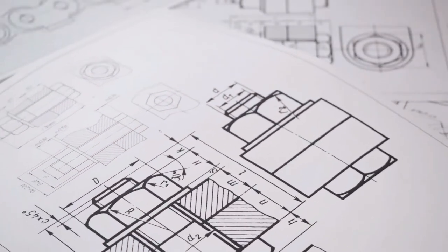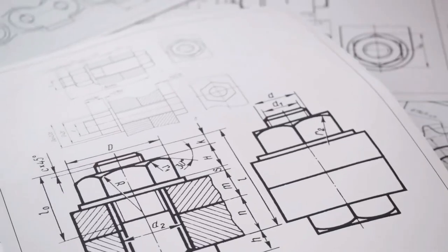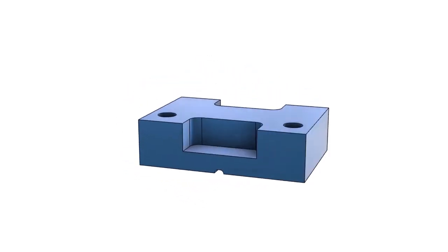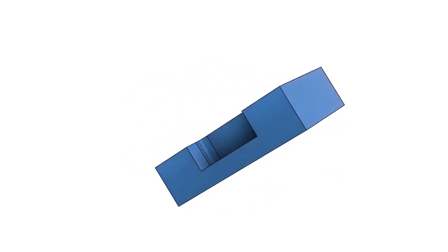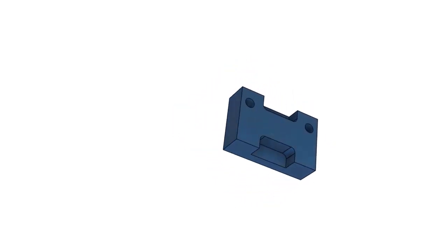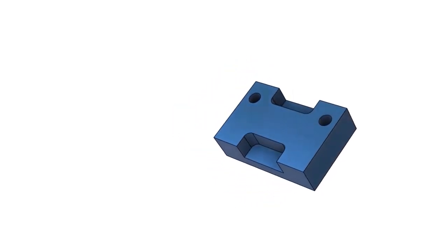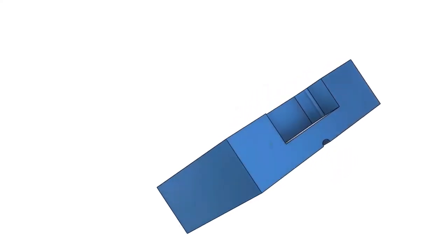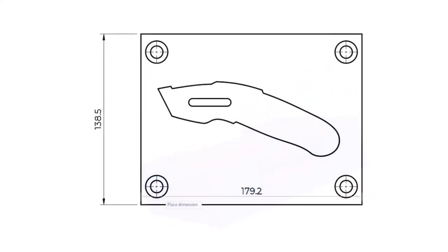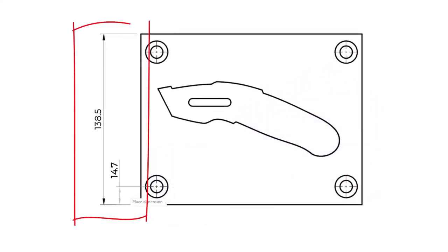But before we go to these complex topics, first, we must learn the basics. Elements of dimensions. As we previously mentioned, dimensioning is necessary to define the shape and form of an engineering component. In other words, with the use of dimensioning techniques on the engineering drawings, we define physical boundaries of the component like size and location of the different features. On a drawing, thin lines with arrows on the sides and a number in the middle, or on the side, is how we represent dimensions on the engineering drawings.